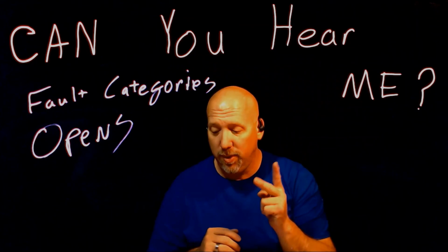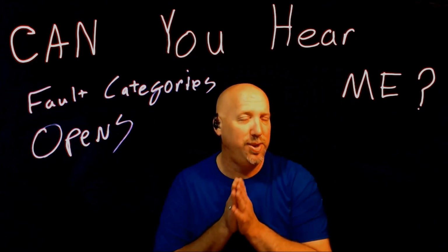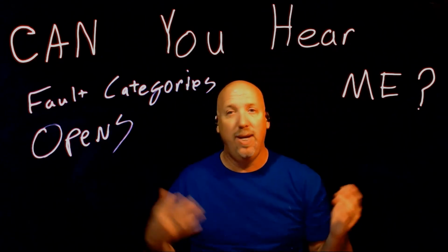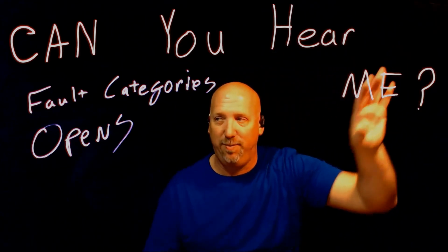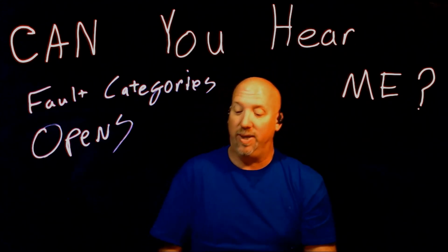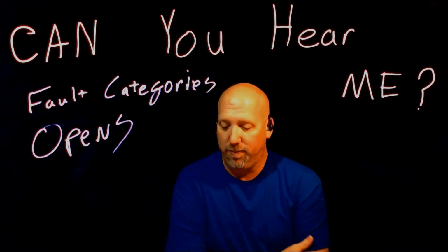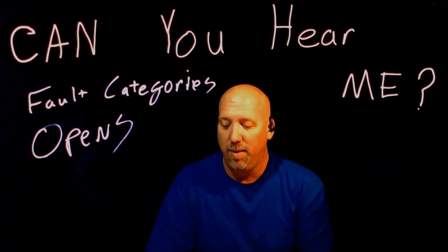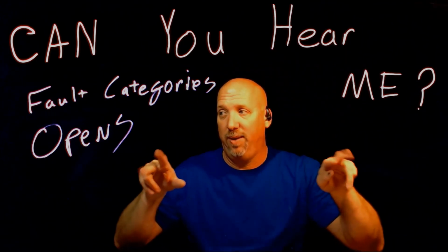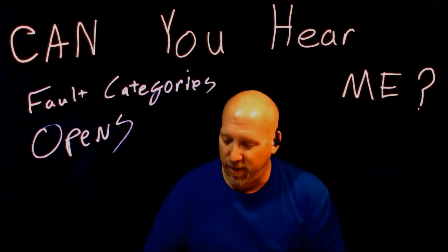Connect a two-channel lab scope. Again, digital storage oscilloscope, lab scope, oscilloscope, two-channel lab scope. I said we're talking about informational systems. A lab scope is what you have to have. The DSO, the oscilloscope, is dire to what you're doing here. Put the two-channel lab scope on the network at the DLC and the working module, and one that is not communicating. So you can actually see the difference in communication on one that's working and one that's not. So be aware of that.